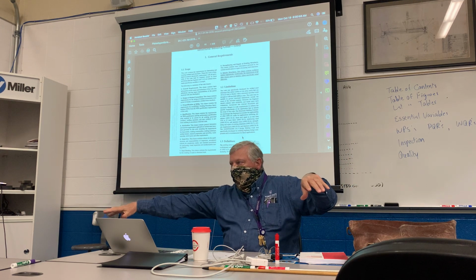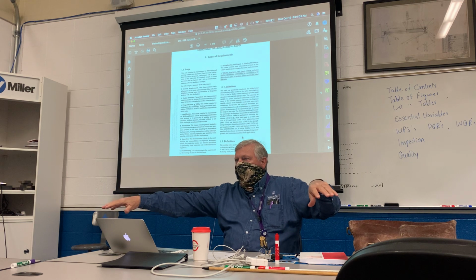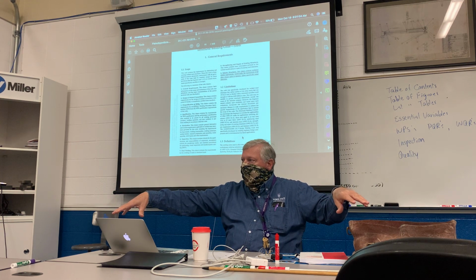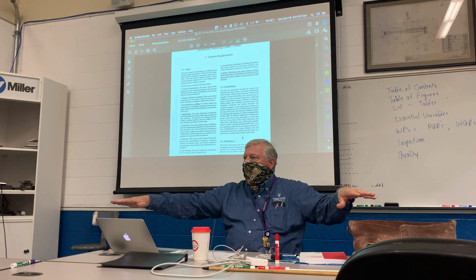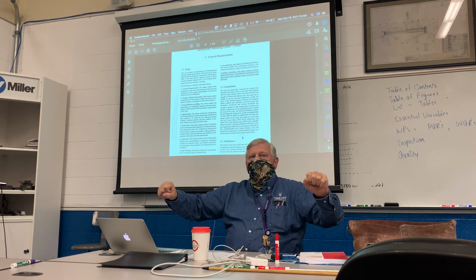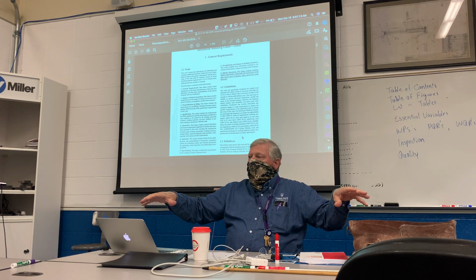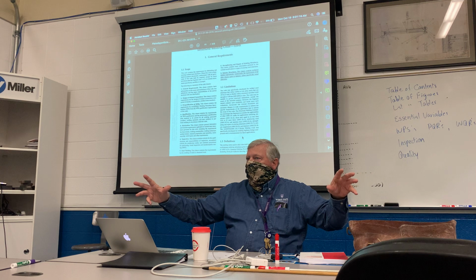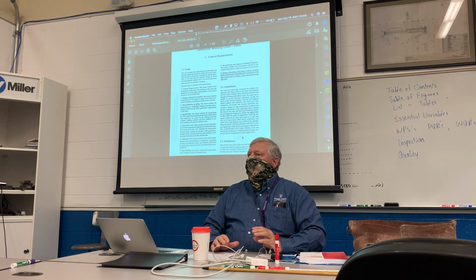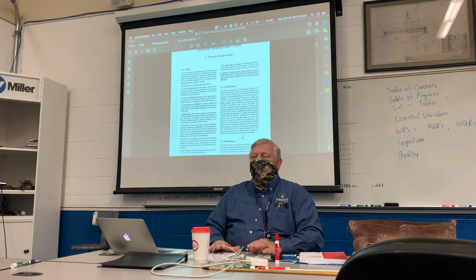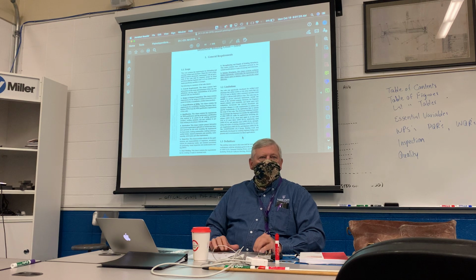Reinforcing bar, rebar, is another one. Why? Because now we have welded rebar. We used to not have welded rebar. After 1984, when the Mexico City earthquake occurred, and 80% of Mexico City fell to the pavement, it was because they were welding unweldable rebar. Why can't you weld rebar? Brittle. Too much carbon, way too much carbon. But now they make a weldable version. How do you tell the difference? How do you tell the size of rebar? Really simple.